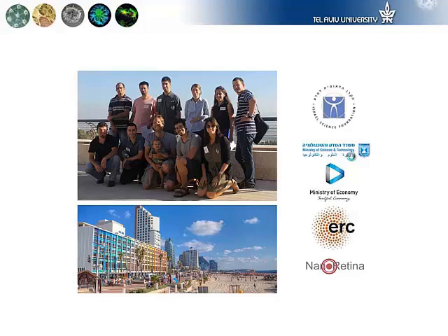Well, it really depends where you're aiming it. If you're aiming at optical stimulation, then it's pretty easy to make very small features. We can go down to 1 micron, 2 microns. As far as the transfer mechanism, it's quite easy. When you want to transfer an entire circuit, including very long conducting tracks, this is a little more challenging, but it really depends how you do the process.